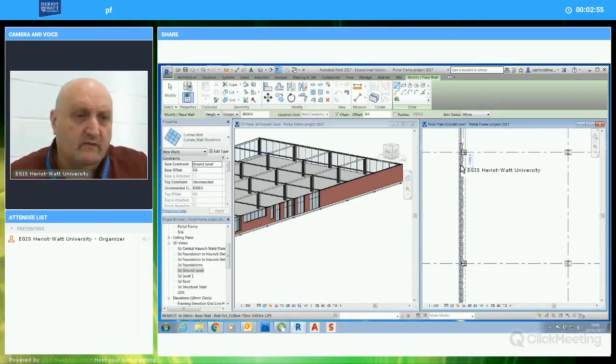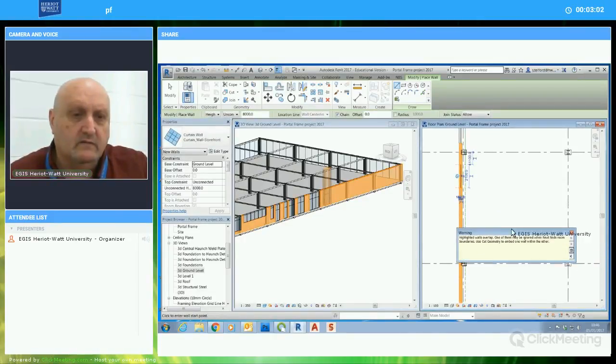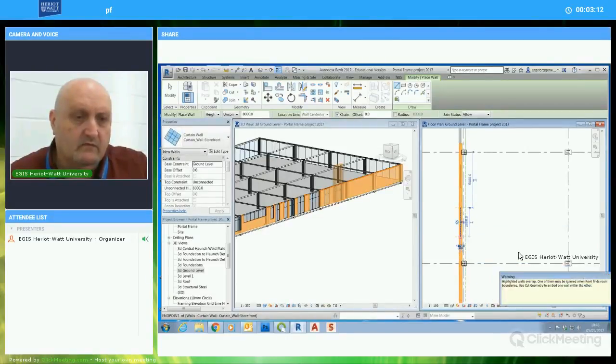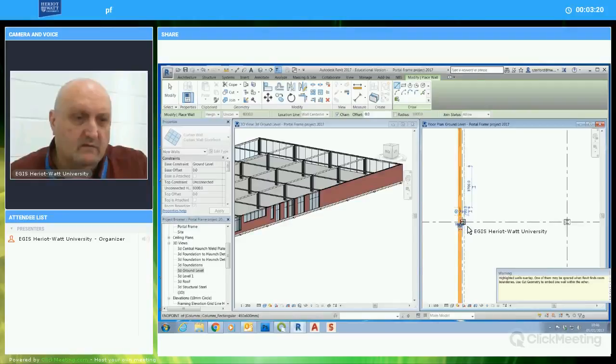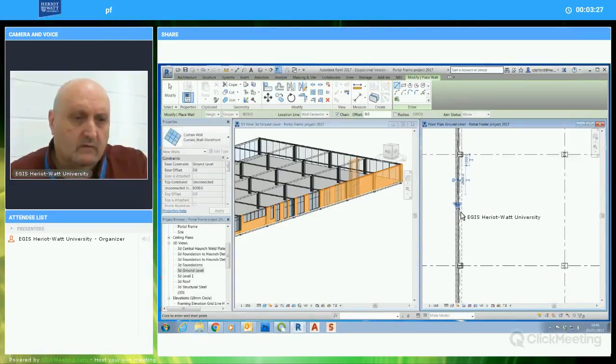I'm going to put in some more of these curtain walls in here. Now this, you can ignore this, just ignore it, shut it down. And I'm going to put in a few more of these curtain walls embedded inside. And here, move that out of the way. A single escape. I'll put a wee one in there so it doesn't have a clash with this architectural column. And I'm just going to make a few of these.